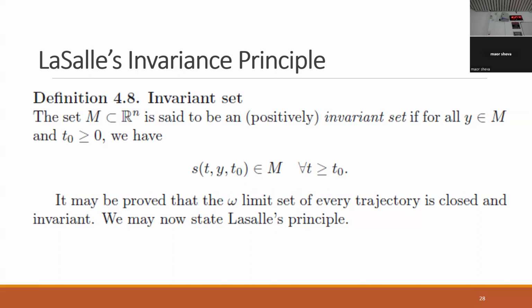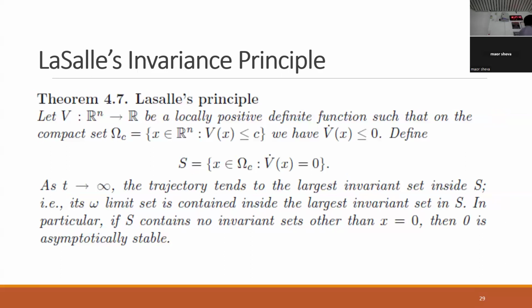We may now state the LaSalle principle. And the LaSalle principle says that let V be a locally positive definite function such that on the compact set omega we have V dot smaller or equal to 0.